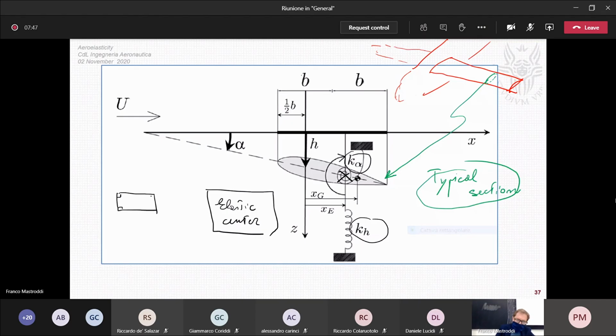This is a section, a structural section of your wing, and these are spars, web, and these are stringer. And so if you consider your section as composed by sub-elements like this, stringer, spars, and web, you have a special point known as elastic center here.